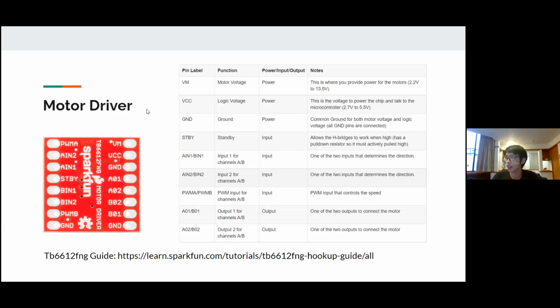it connects to the 2 motors that you have, and it basically controls how much current is applied to the motor. I think I mentioned in the second session that the motors, one of those angled motors or a straight motor, are both similar. They have a gearbox within, and there's only 2 pins that you connect it to. If you just connect it to, say, a power supply, it will have a fixed power input,